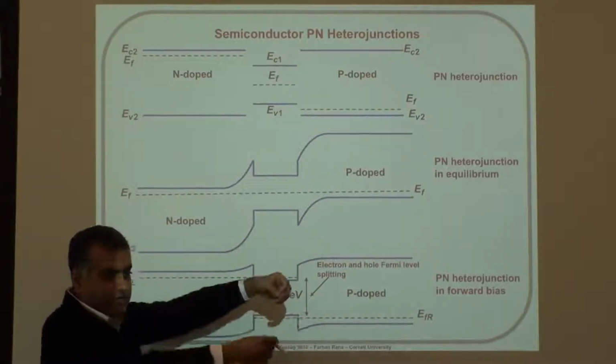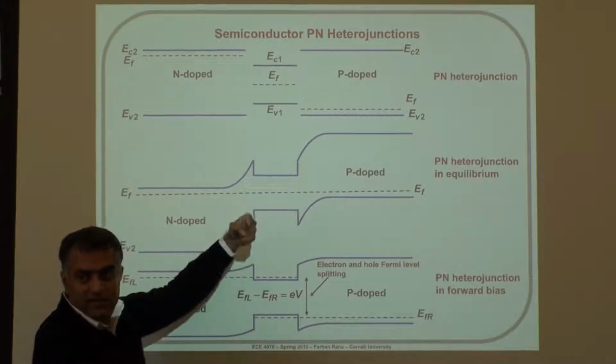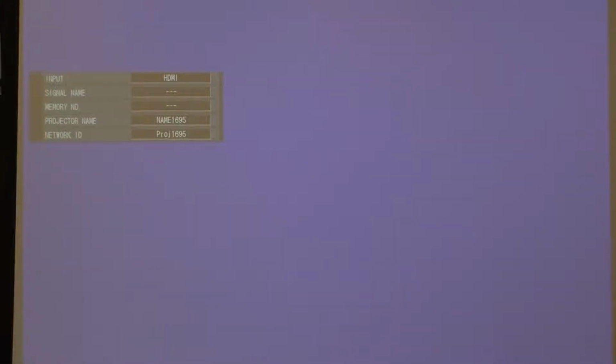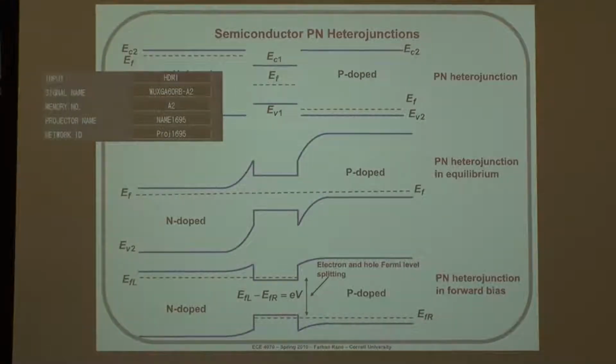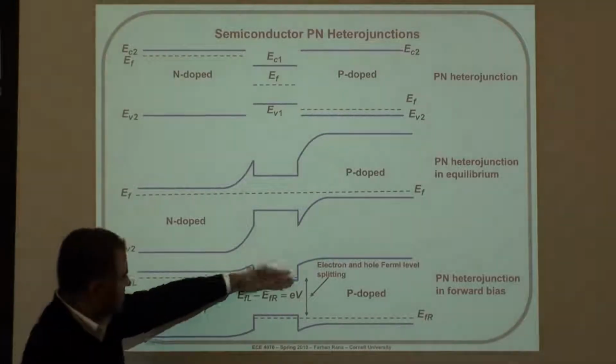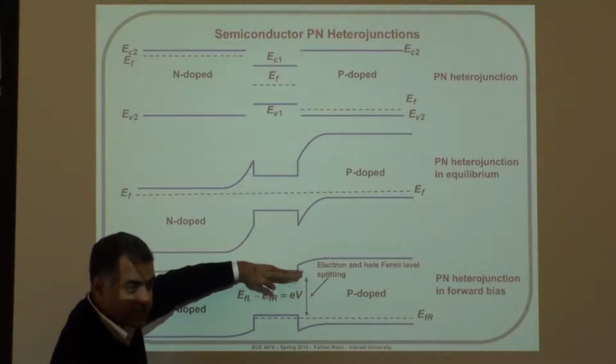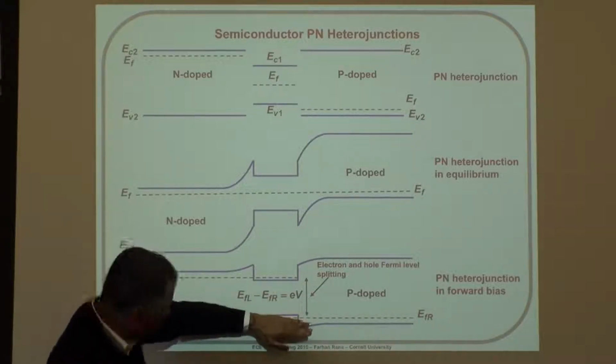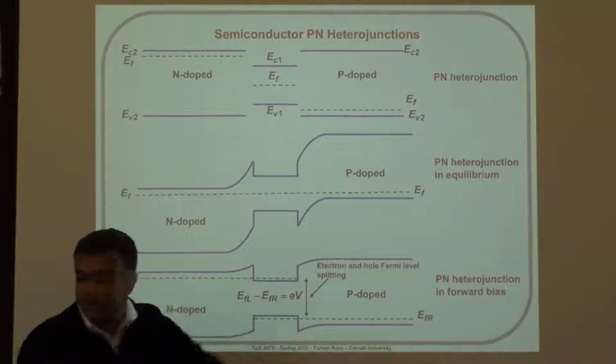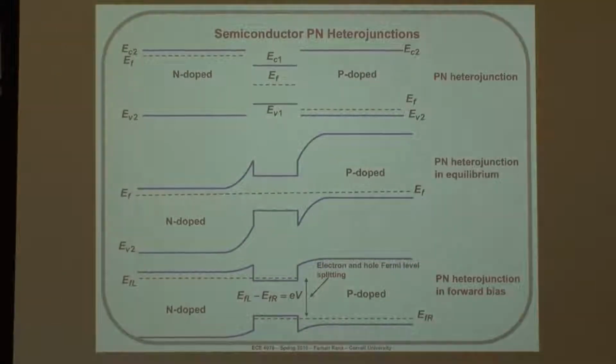Just like, remember, for the ballistic FET, source and drain, you have two Fermi levels that separate by drain voltage. It's very similar here. It's really no different. And this is how you have created population inversion. Now your Fermi level is in the conduction band here, and the Fermi level for the valence band is here, and that's how you create this sort of situation, and you get a negative absorption coefficient.